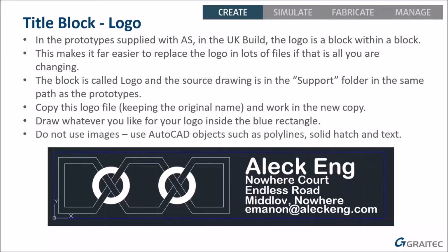Please do not use images. Some people do, and some people think they get away with it. But images have two key problems. When you insert an image into an AutoCAD DWG, it does not embed that file into the DWG. It's really, really hard to make it do that. What it usually does is link to the file on disk.